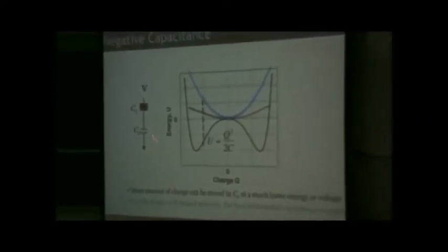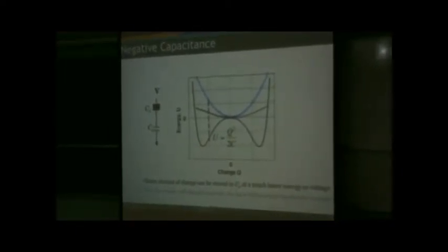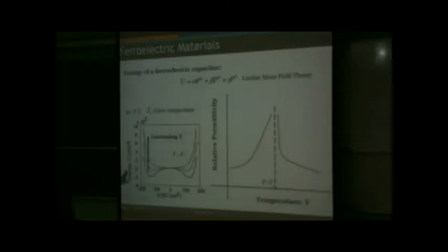So I said that if I can put a ferroelectric material and stabilize it in the negative differential capacitance, then I'm going to get a voltage amplification at the internal node. It's an electrostatic voltage amplification, very difficult to measure. But we can measure it by seeing that the total capacitance of this network has gone up. Okay? So again, as an academician, I want to look at that system. I want to put two capacitors in series and see if the capacitance can go up or not. We will show some experimental results on that, but before that, let me talk about the ferroelectric material a little bit, which will help us understand the experimental results.